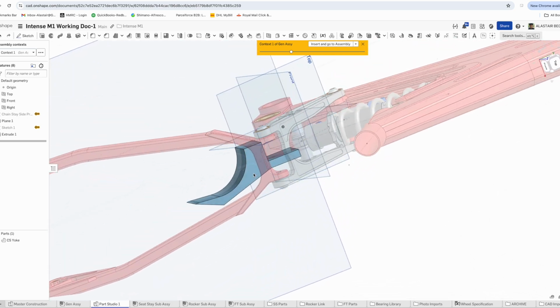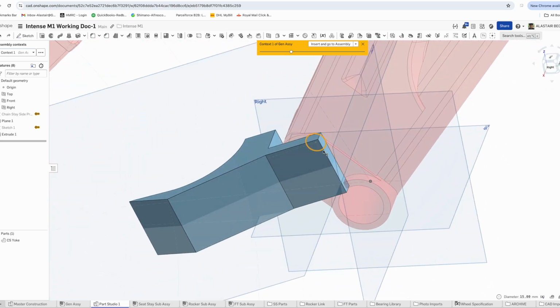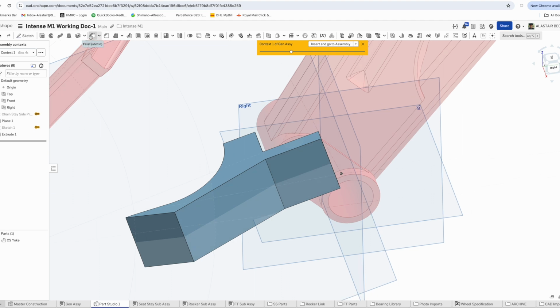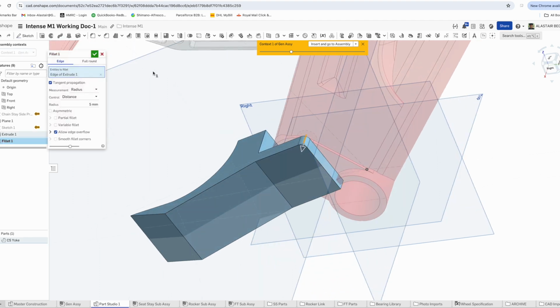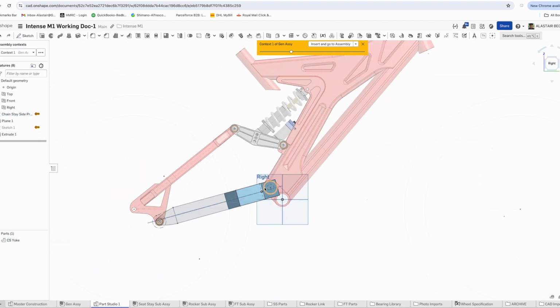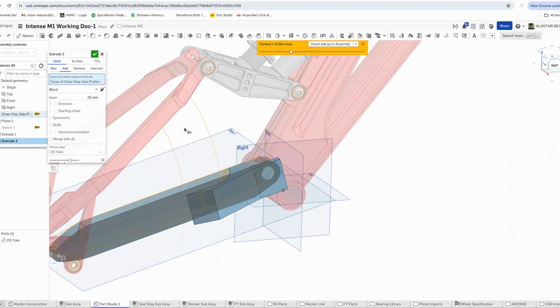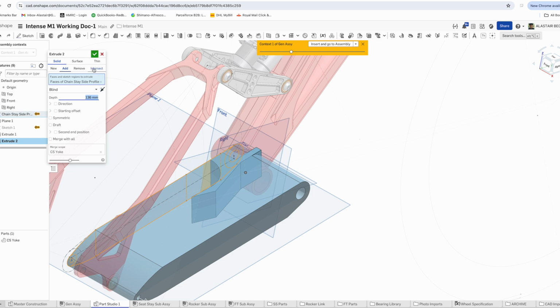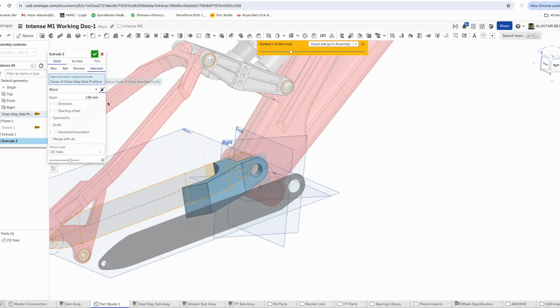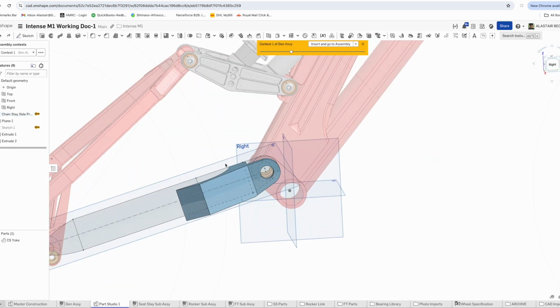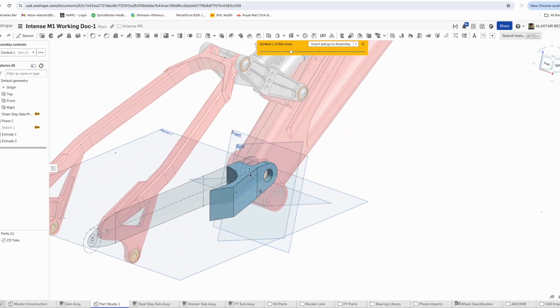Because we've extruded that top-down profile, instead of adding the rads manually in there, we can keep using that side sketch that we had, and use a cool feature that Onshape has called intersect, where you can use a sketch to cut through instead of physically extruding another part. It'll modify the part that we've got. So it's a super useful tool.